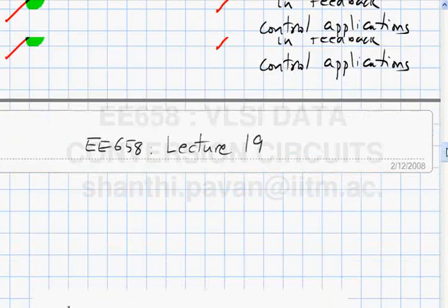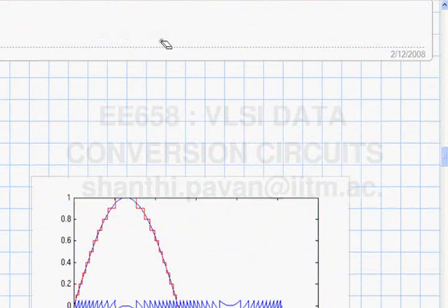So so far we've seen what is often called low frequency characterization or static characterization of an AD converter, because the first thing you do when you get an AD converter is put in a slow ramp and make sure that the output looks like a staircase. If that is not happening, then you know something is fundamentally wrong, and then you go and fix it. It doesn't make sense to start putting in high frequency sine waves when the low frequency stuff doesn't work. Alright.